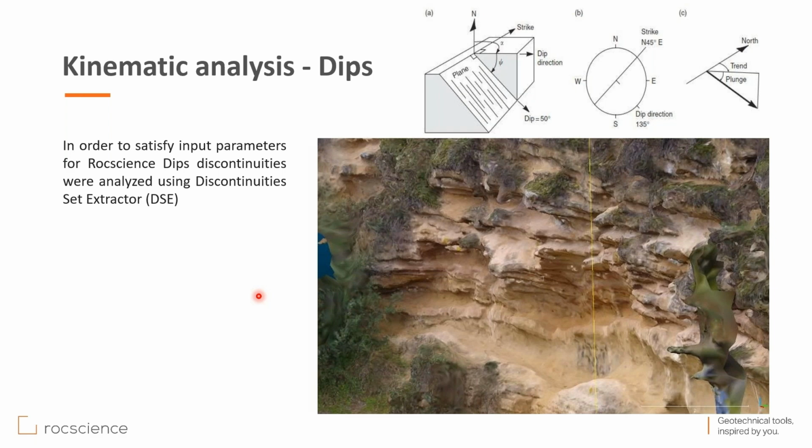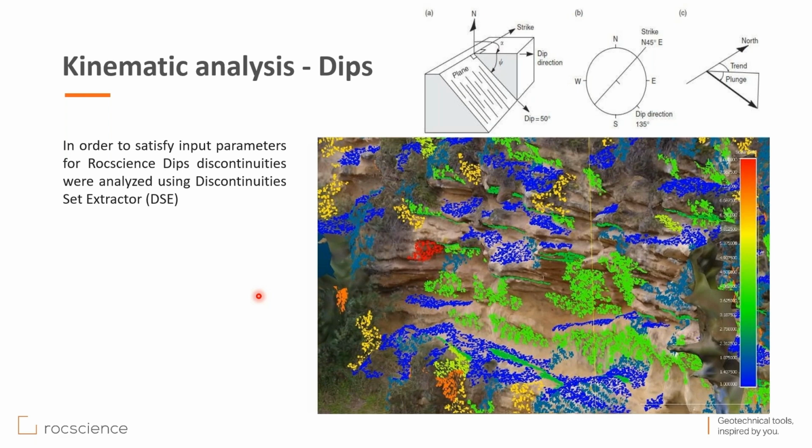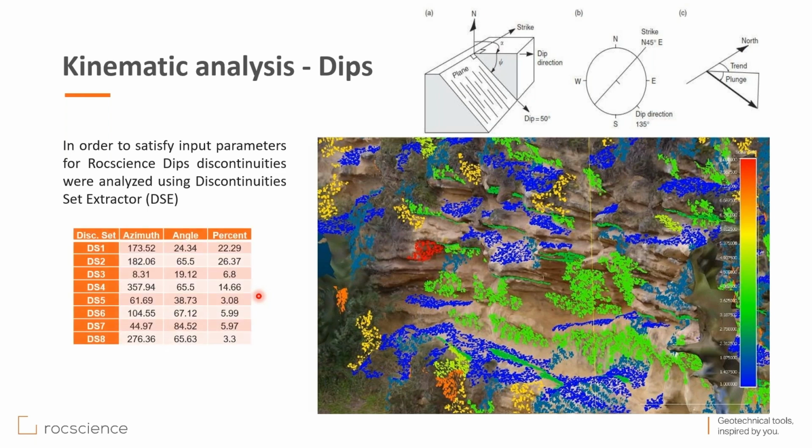We used for the present project the Discontinuity Extractor software, which is open source. You can find it very easily online with a simple search on Google. And you can see that photogrammetry produces a very large number of discontinuity cluster orientations compared to the mapping procedure. How we did this is the following. In the first stage, the raw photos were aligned and a preliminary model was created. In the next step, the preliminary model was referenced by landmarks that could be observed in our small video.